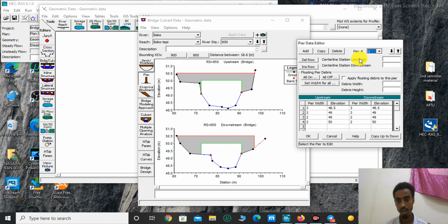So you can enter the center line station at upstream. Maybe at 80 you are required to design, or to be at these stations. At station 80 you can fix your center line, but it is not recommended to construct a pier in the middle of the river, because it is most appropriate to locate the pier at another site, except if it is absolutely necessary to design it.